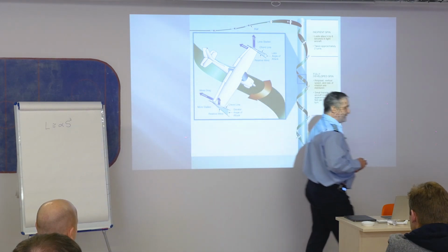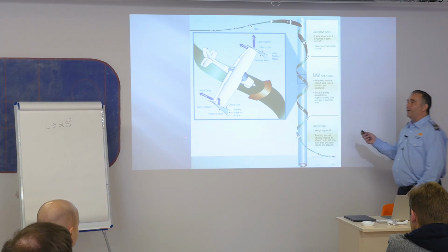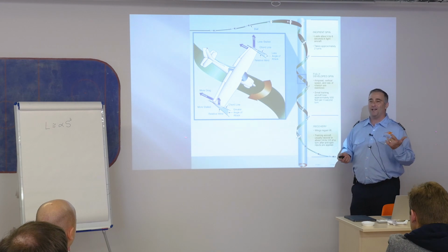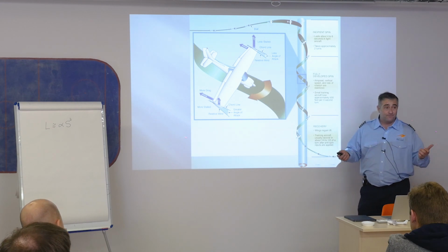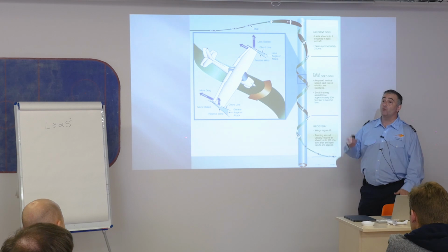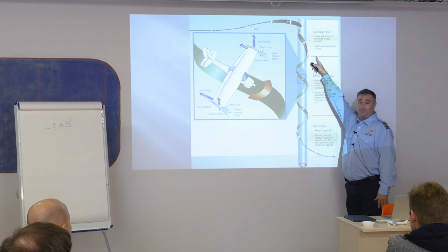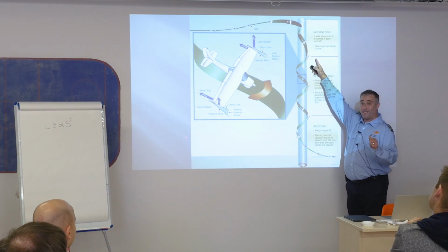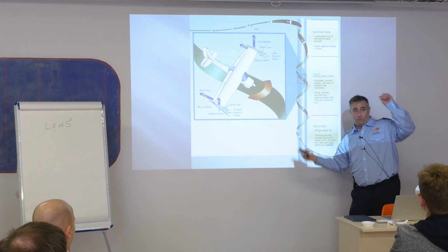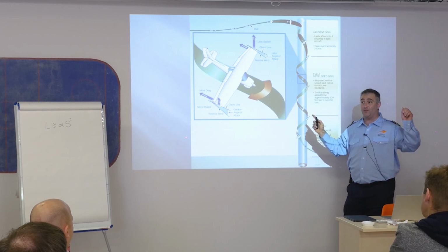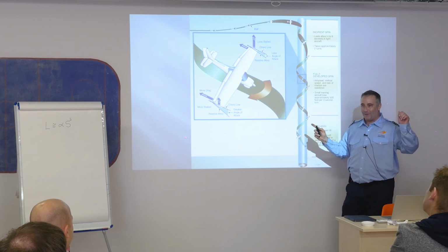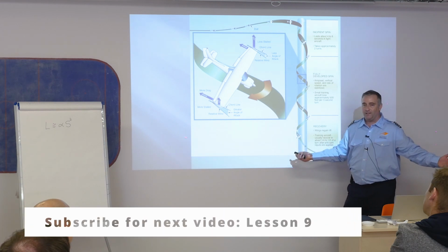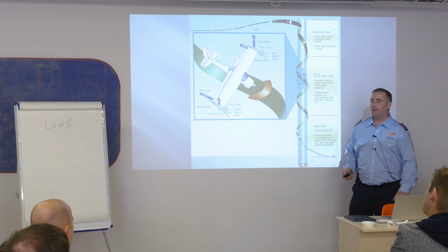Okay? All right. By the way, there's a lot of emphasis on the spin, and I know pilots sometimes get a little bit of anxiety from it. It's fun. It really is. And unless you know how to make that happen, you're not going to make that happen. I promise you that while you're training, you may get a little bit of a wing go left or right while you're doing your stalls, but it will not spin, okay? Just release the controls, make the airplane fly again, and then start a climb, all right?